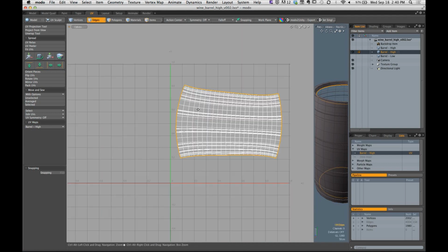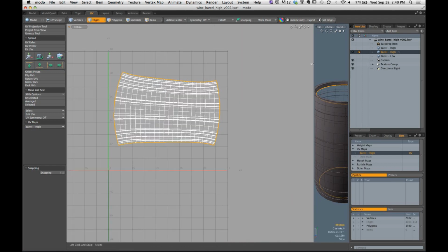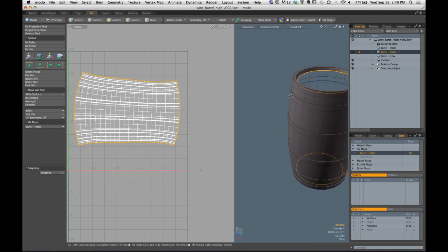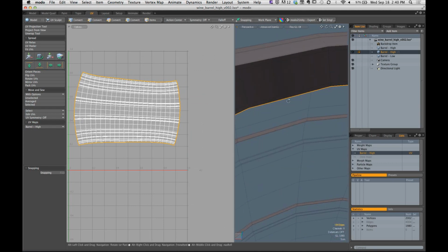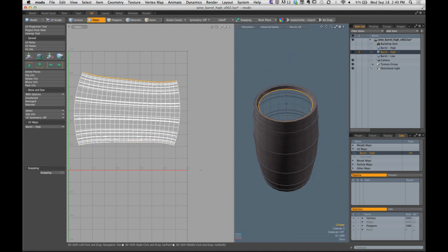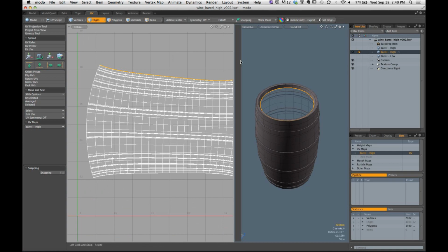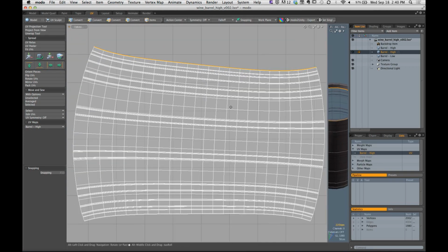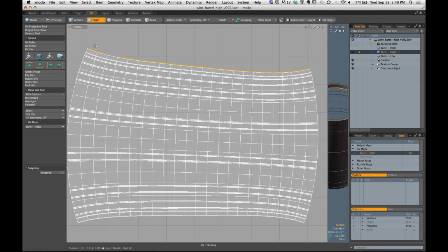If you double click on it, you select the entire border of your UV island. Don't do that. However, this is why we have a UV window over here. I can double click that border edge, and you can see that just that top row has been selected. So I need to align that edge to itself and make it perfectly vertical.